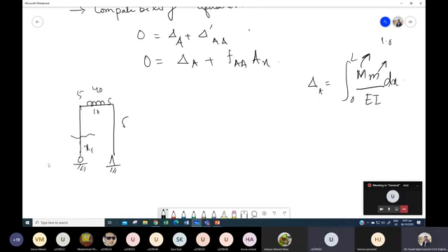Okay, let's call this as our x1. Yes, sir. And then the second section will be UDL से here. पहले, sir. UDL पे. Let's call this x2. Third section, let's call this x3. Fourth section after UDL will be our x4 and the fifth one over here. So if you remember, we would take a section at the point where some load is acting. For example, if there is a point load, then we should have taken 2 sections on this beam. Since there is no external load on this member, 1 section will satisfy our condition.